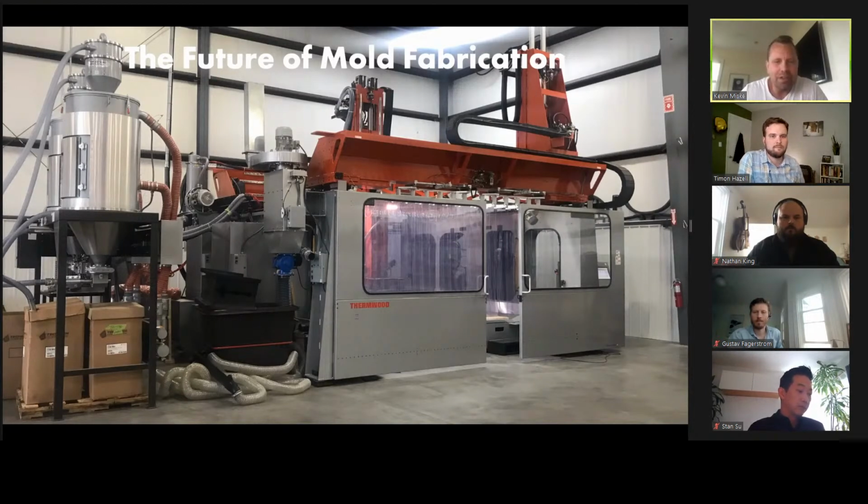So this is a Thermwood LSAM system, which is large scale additive manufacturing, that has the ability to produce molds for us that would be 3D printed with a polymer and then CNC machined to the finished product, which greatly increases our ability to control tolerances, and it gives us the ability to produce the negative, so we could go right into production on spraying pieces into a mold that is highly durable, that requires very little maintenance in between passes.